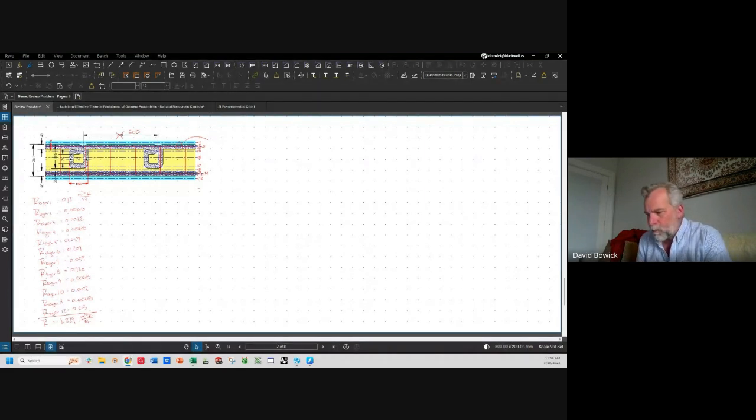The one thing I'll remind you is that the temperature change is proportional to the R value. The layer with the highest insulation has the highest temperature difference.